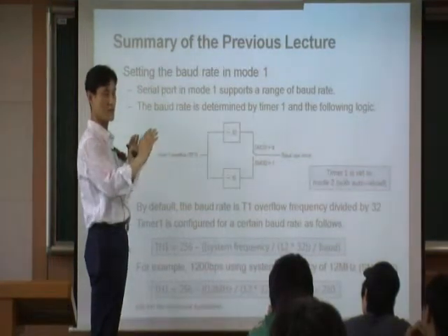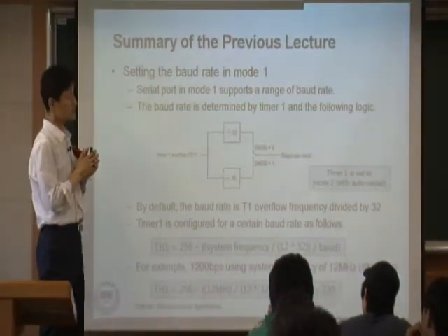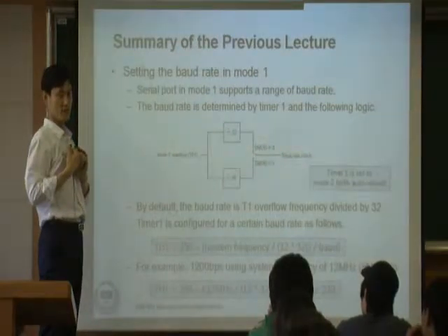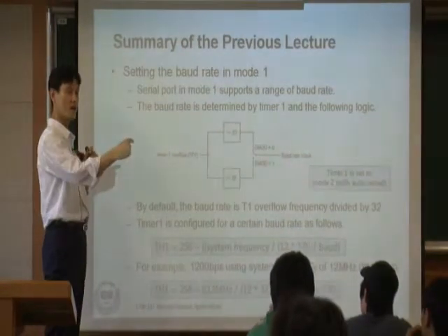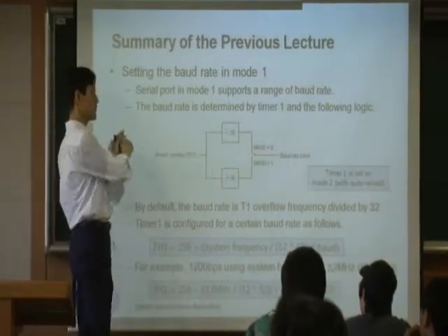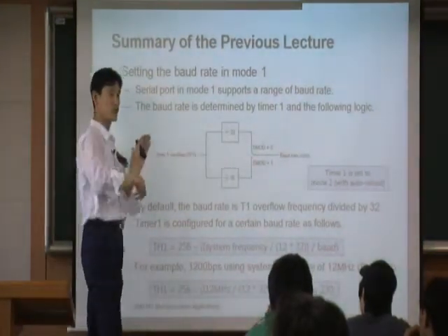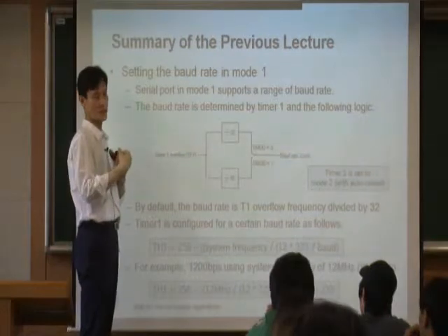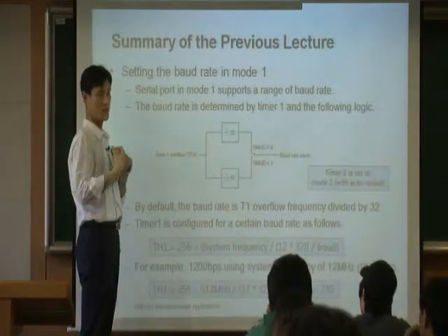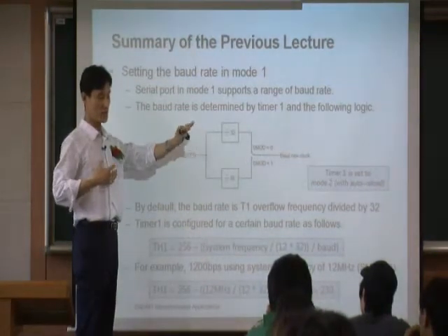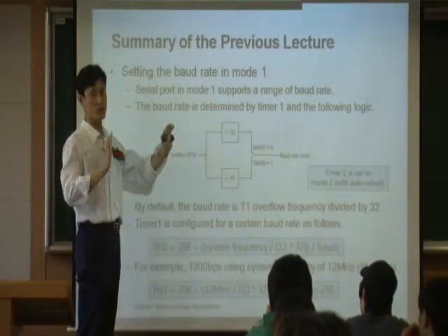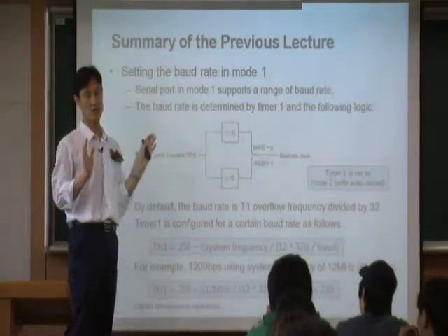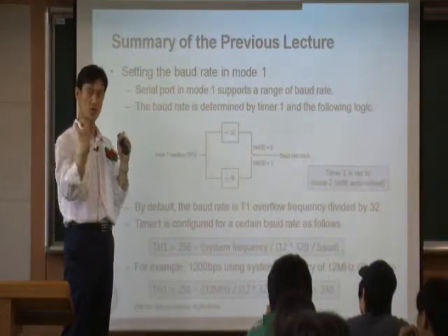And you transmit. And also the receive, right? From the receiver's point of view, the receiver is receiving the clock. So by simply looking at the clock, you can decode and recover the bits. Therefore, transmitter and receiver don't have to agree on a certain BPS. Initially, they don't need to know, because you have a clock.